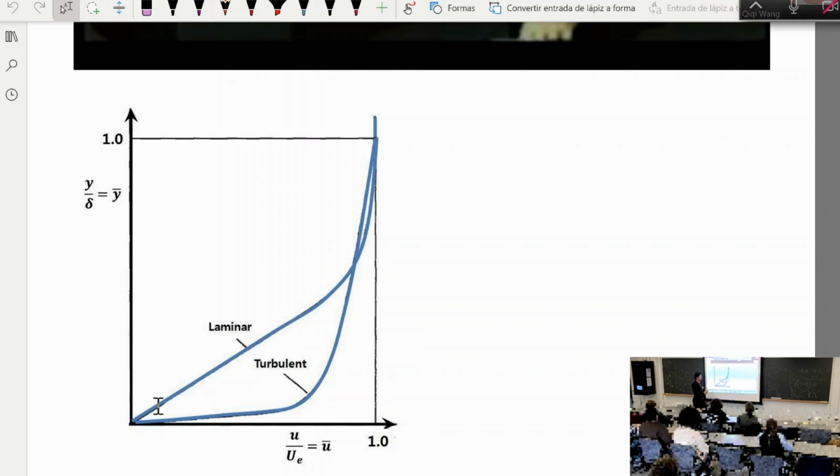But the ratio is much smaller for a turbulent boundary layer. It's typically in the range of 1 point something as opposed to 2 point something on the zero pressure gradient. Okay, and if you find a turbulent boundary layer that has a shape factor that's like 2.6-ish, it is in a very adverse pressure gradient. Okay, and potentially close to separation.